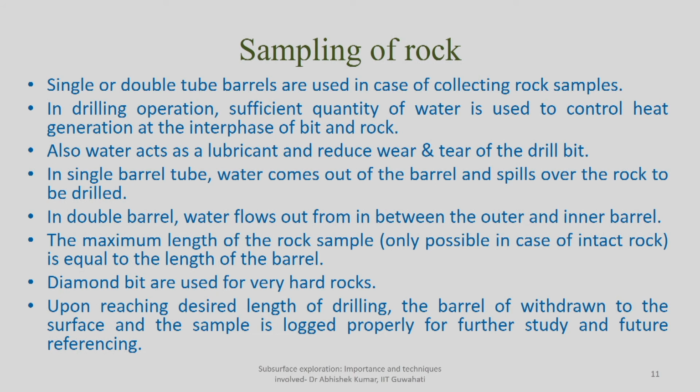So you can go for double or single barrel or double tube barrel. It can be used for collecting the rock samples. In drilling operations, sufficient quantity of water will be required, because as the drill bit is rotating, a lot of heat will be generated. So in order to ensure that heat will not cause any problem or hindrance in the operation, and also to minimize the wear and tear of both sample as well as the drill bit.